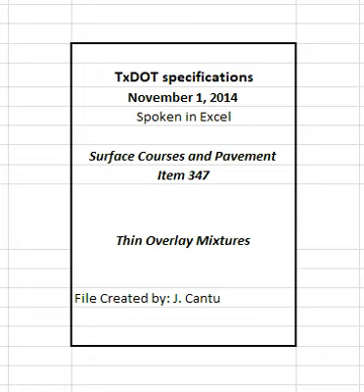4.4.2.2.8 Approval of Lot 1 production. The engineer will authorize the contractor to proceed with Lot 1 production, using JMF2, as soon as a passing result is achieved from the department's or a department-approved laboratory's Hamburg wheel test and from the department's overlay test. The contractor may proceed at its own risk with Lot 1 production without the results from the Hamburg wheel test and overlay test on the trial batch.